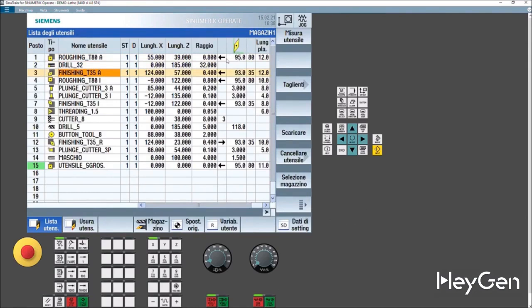There's a collar for dual turret machines. Dual turret machines sometimes have a collar on one turret while the other works. Star probes, various drill bits, mills, even angular head mills are available. Favorites are already visible. In ShopTurn, if a tool is missing, just insert it. You can prepare the tool table beforehand or insert tools during ShopTurn programming. If a drill bit is selected in position 2, it needs to be placed.